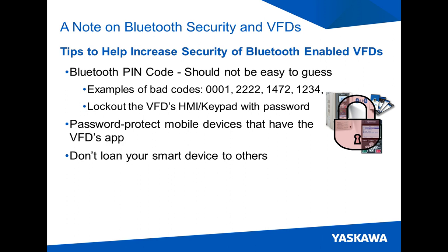So you want to lock out your VFD's HMI keypad with a password if you plan to, in addition to the Bluetooth pin that you're using to secure the connection. And you do want to password protect mobile devices that have a VFD's mobile app installed on it, especially if you're using that mobile device frequently in your facility or in that environment. And then you might not want to loan out your smart device or mobile device to others if you know that it's a tool that you use in your work and it could potentially or inadvertently change some drive settings.